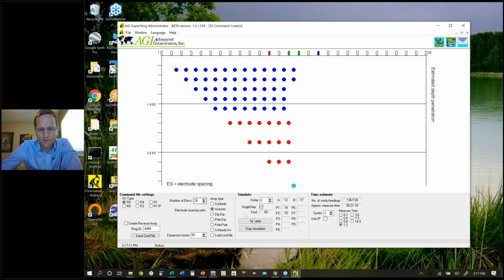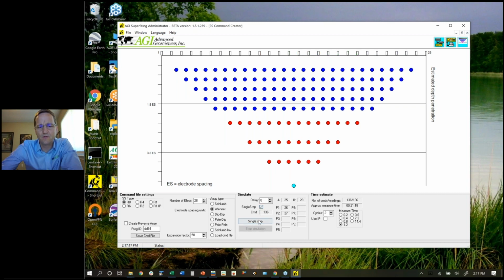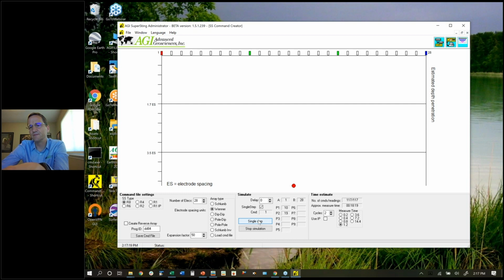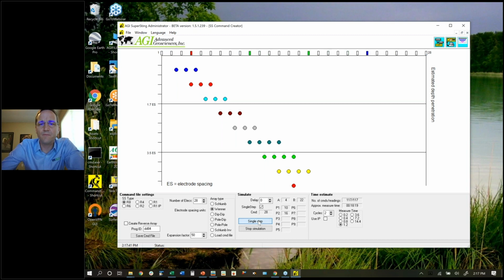If I was to go to Wenner, everything is always equal. The spacing between any of the next nearest electrodes is always equal. All 4 move on every single reading, so there aren't as many unique positions. The benefit of Wenner is that the signal is extremely high. In between, that quarter space is a very high voltage. So the best thing to do, I think, would be to fit the protocol they're asking for these grounding wells.